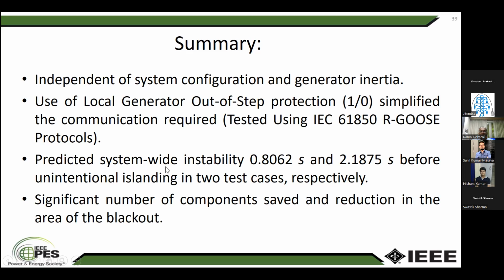We predicted system-wide instability 0.8062 seconds and 2.187 seconds for the two scenarios before an actual unintentional island. So for a RAS, 0.8 seconds in terms of computer hardware is quite a bit of time to do the processing on an actual RAS on a device. And we could save a significant number of components, and the region of blackout. So thank you, everyone. This concludes my presentation.